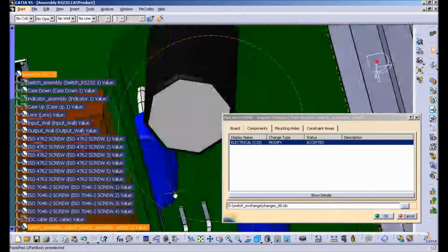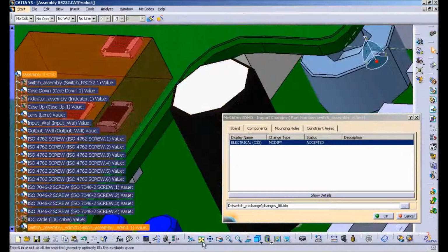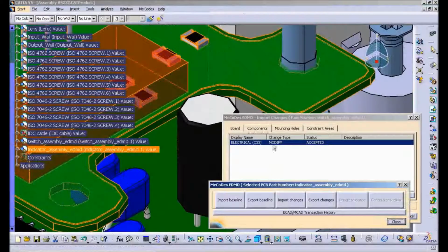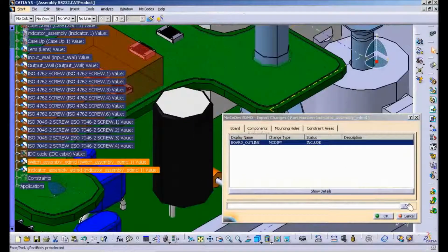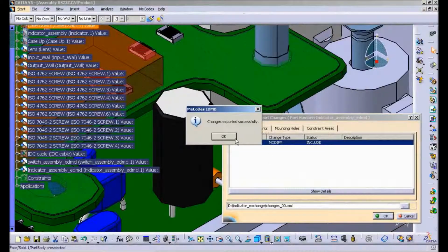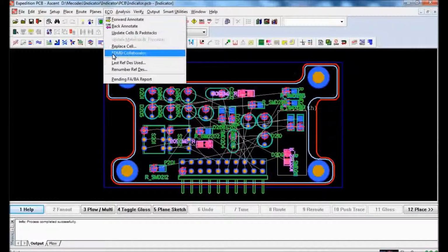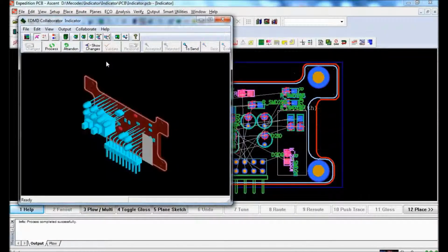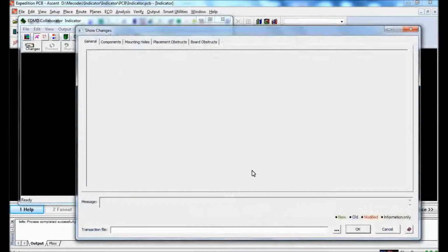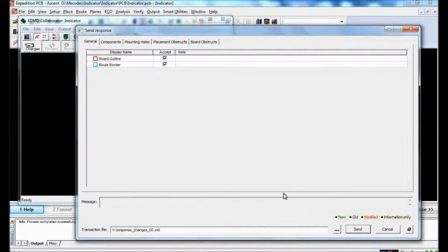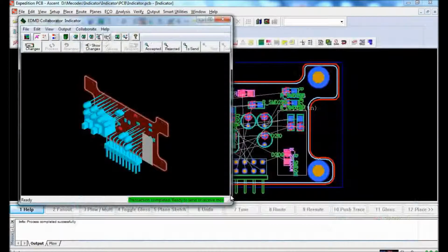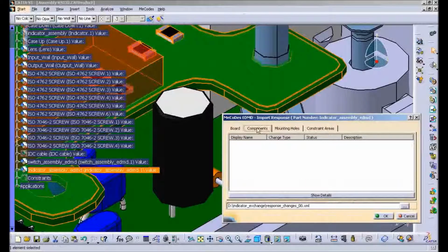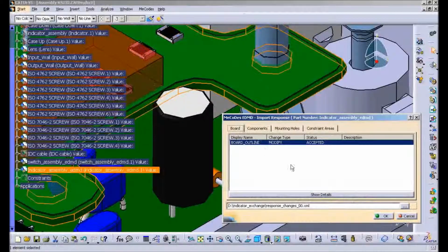The upper board designer validates this request and approves it completely. Now the MCAD designer can approve the request from the ECAD bottom board designer, indicating that movements of these components are now acceptable and verified and can be performed. Now both ECAD designers finish their designs and send a final design with all elements of the boards: outline, components, routes, holes, masks, screens, etc.